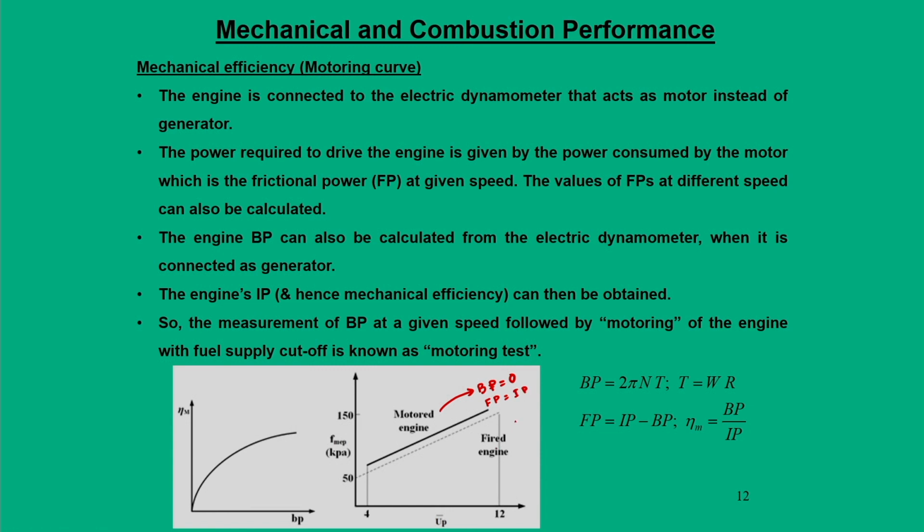But in a fired engine, where the dynamometer actually applies load to the engine, your brake power is not equal to 0. Of course, friction power is also not equal to 0. So, this is a real sense and this is an ideal sense to estimate the friction power, and this is what the concept of the motoring test is all about. In one case we run the engine in motored conditions, and in the other we run the engine in fired conditions. Based on that we can calculate the friction power.